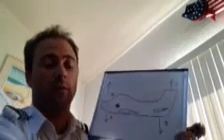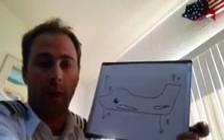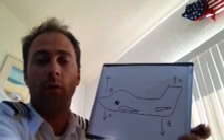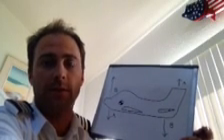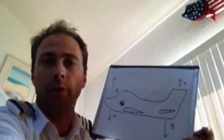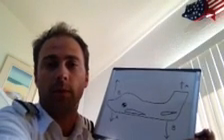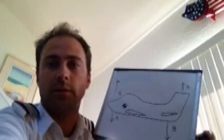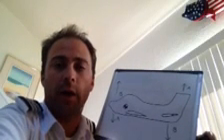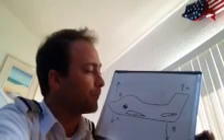So the pilot activates the trim tab by a control wheel, usually located in the console or between the pilot and co-pilot seats. It's a vertical wheel. It's rotated forward for nose down trim, backwards for nose up trim, and is usually attached to the trim tab via a series of cables.